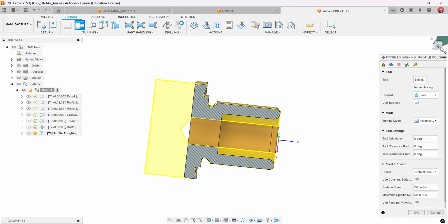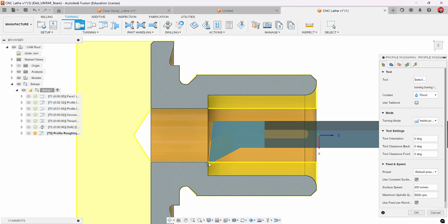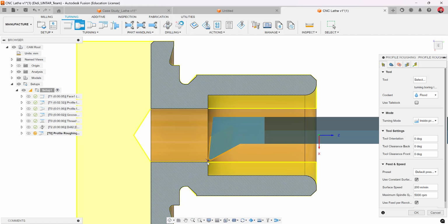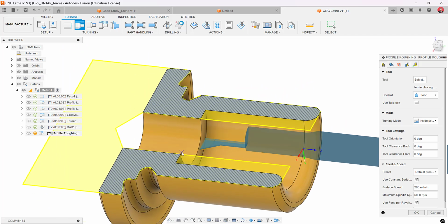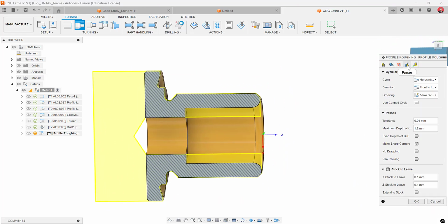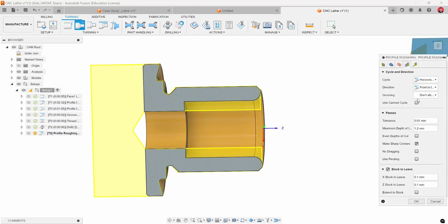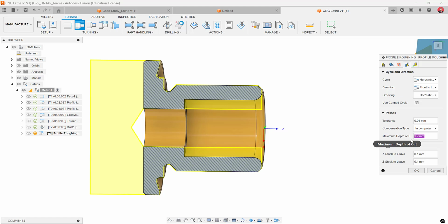Okay, let's see from the top, and then the operation will be like this, and then retract. Yeah, it's enough. See, the retraction will be. Yeah, that one is round already. It's okay. Then I will use horizontal passes from top to bottom. Don't allow grooving since there is no grooving. Use scan cycle in computer, and then I will use 0.7. Stock relief will be 0.1, 0.2.